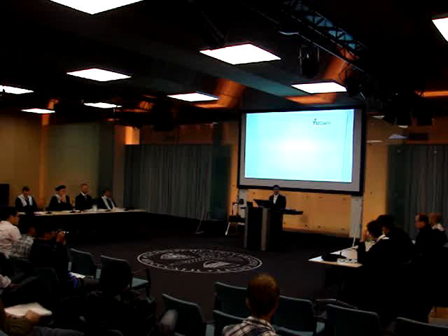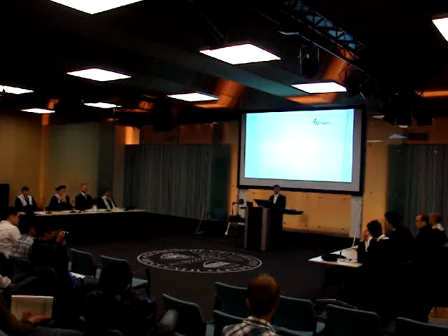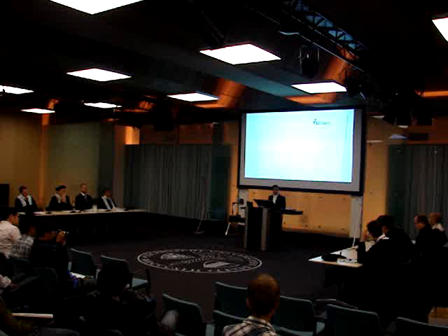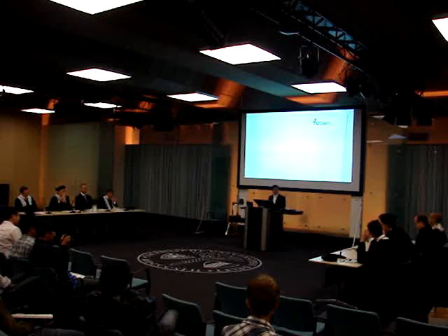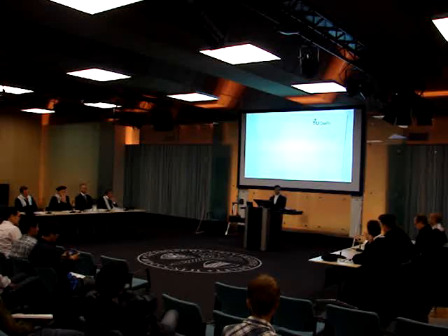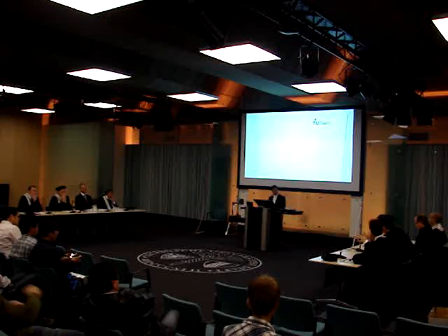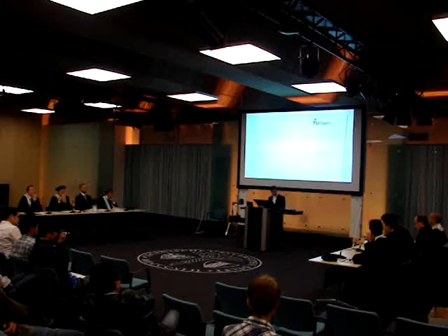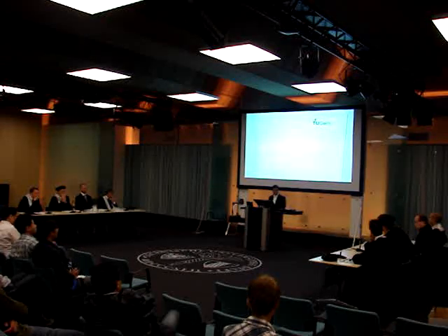What happens there? I think in hardening, the RVE size grows. You need bigger microsamples to get a statistically homogeneous response. Okay, so you agree. Right. So the situation we have is we've got elastic RVE, which is about a few times the aggregates. Yeah, 3, 4, 5 times the aggregates. Then we go pre-peak hardening. The RVE grows. Then we go softening, and suddenly it collapses to a very narrow band. So I don't think there's a continuity of RVE definition there.